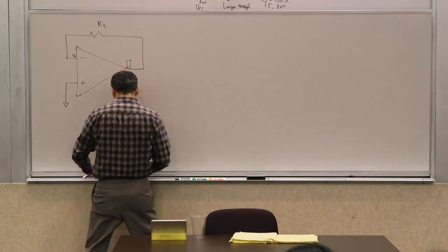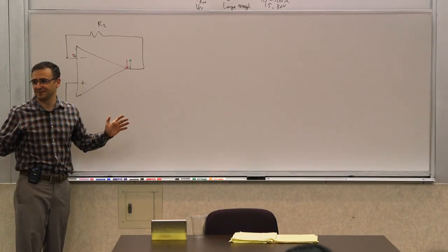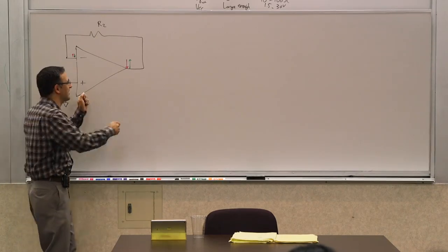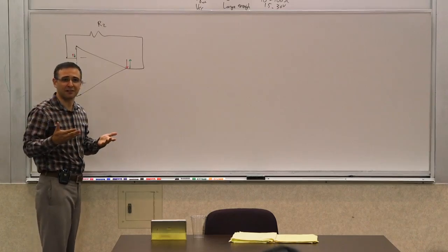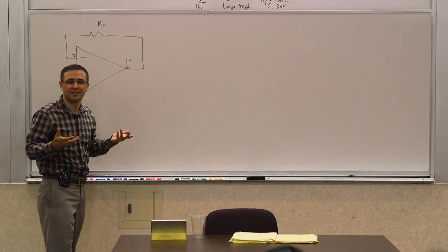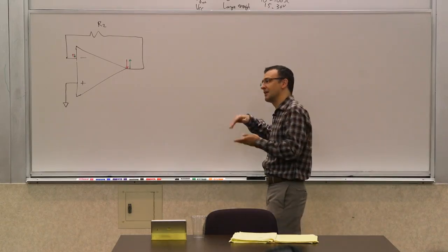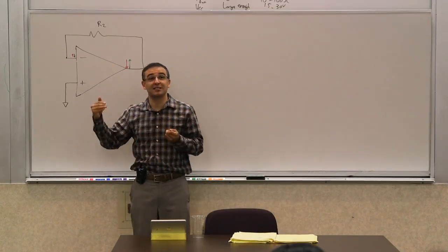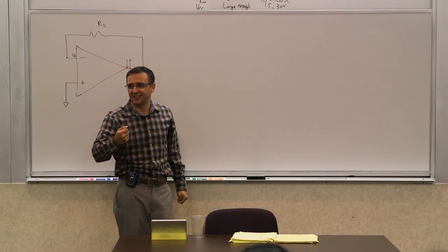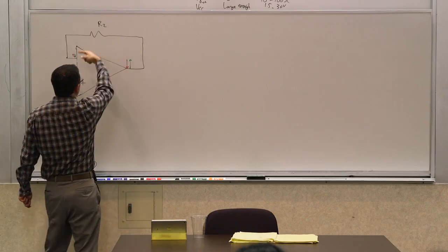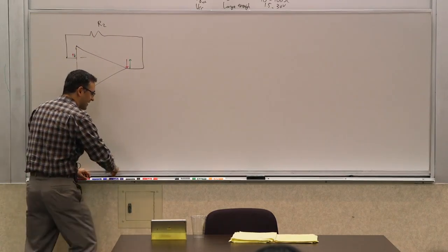So here, this op amp, at least the ideal op amp, is infinitely fast. So the slightest variations it immediately fixes. Now, a real op amp is not infinitely fast. It has bandwidth. It has dynamics, and these are the things that we talk about as we go through this course and other courses. So what happens is that, as a result, there's limitation on stability. And what happens is that if you apply the wrong kind of feedback or too much of it, then you can be in a situation that this can happen.